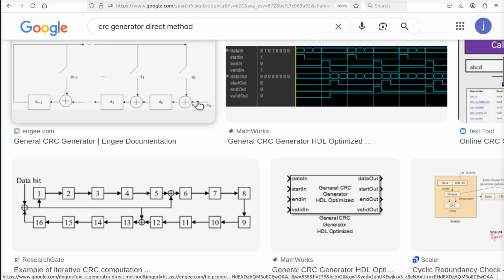The idea is in this kind of circuit, and this is what Ben does, you can hear all about it in Ben's video. There'll be links below mine to his. The data comes in, goes into an XOR gate, and one of the inputs of this XOR gate, and all the other XOR gates in this design, come from the most significant bit that shifts out the left. So each of these XOR gates has the input that's coming from the serial line, the least significant bit here. This one has the least significant bit and the most significant bit coming around like so, all right?